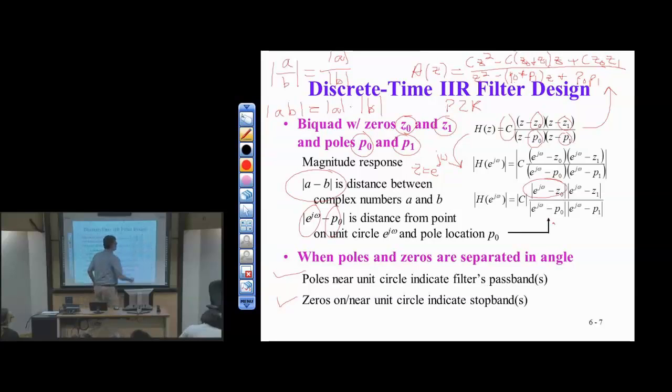If I multiply these two together, I've just thrown away 53 bits of accuracy, which is roughly 6 digits of accuracy thrown away. Doesn't sound like much. And for a biquad, it's not that big of a deal. But in many cases, if I do the unfactoring by multiplying through the poles and zeros, and then refactor back to poles and zeros, the pole and zero locations change because I've thrown away information. The poles and zeros can move around.